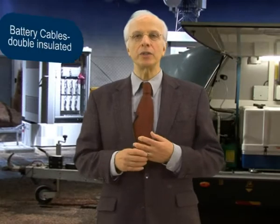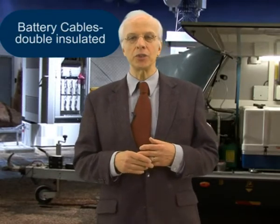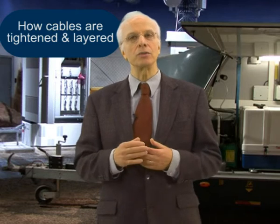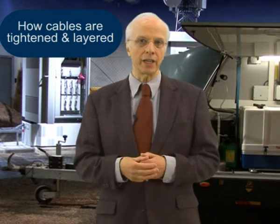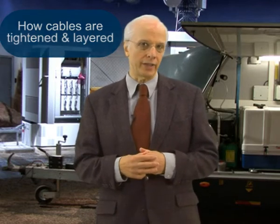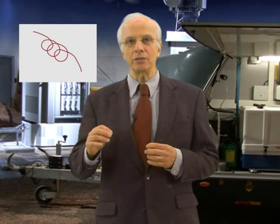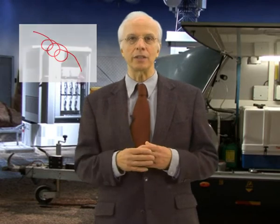When working with battery cables, make sure that the cables are double insulated. The way cables are tightened and layered together is also crucial in terms of their current carrying capacity derating factor. For example, coiled power cables must be current carrying capacity derated due to accumulated heat.